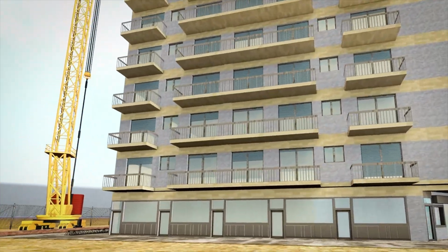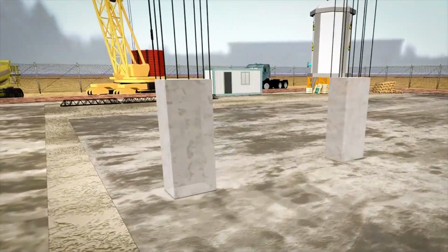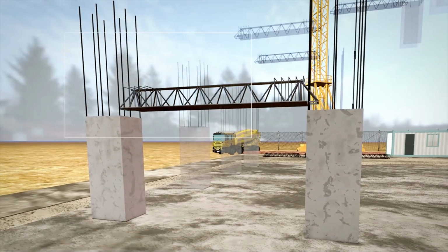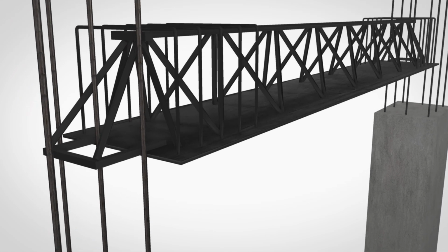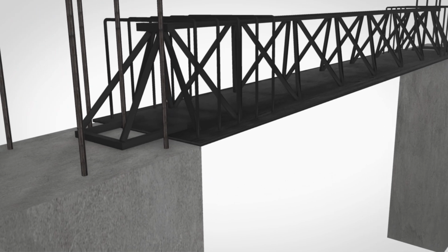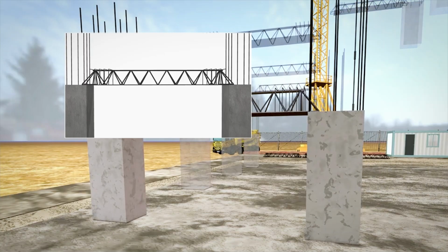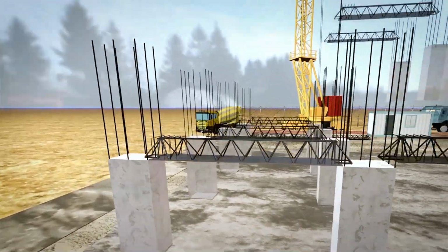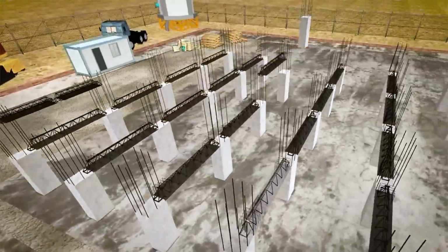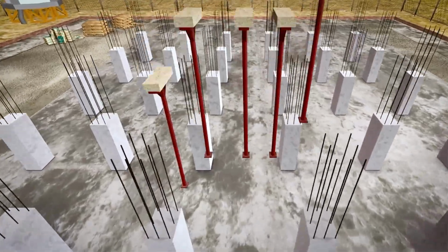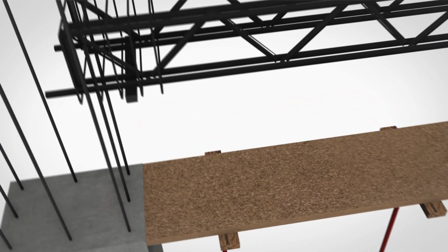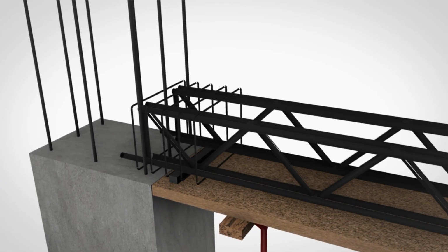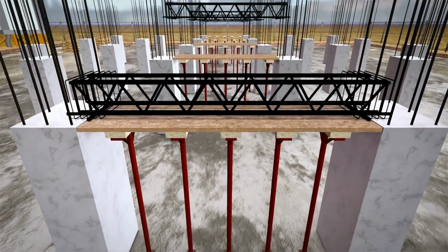The highly recommended products are the MTR A and MTR T beams. MTR A beam, self-supporting during assembly and casting of the deck, and with a steel bottom plate which acts as reinforcement and formwork. MTR T beam, to be formworked and propped up during assembly and casting of the deck, with no bottom plate and completely embedded in the cast concrete.